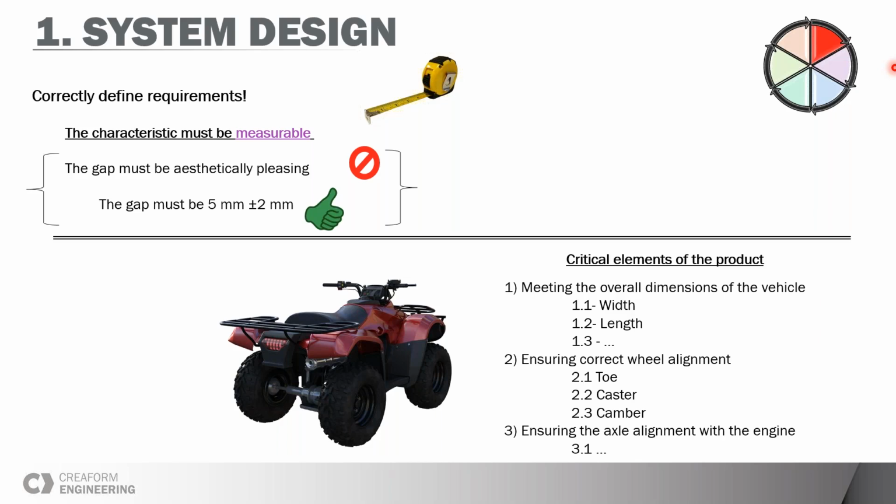That gives you insights on what the tolerance should be, and then in terms of the nominal value, like if it's plus or minus 1 millimeter or something, that's more on the manufacturing process, or like if it's an elastic product versus a hard plastic, then you have to make an engineering decision. A good way to determine that is prototyping.